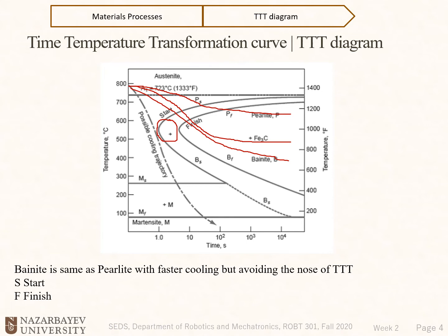So you see that we couldn't have martensite if we change temperature slowly, but we could have a different structure, which is martensite, and it is much harder and, let's say, stronger than other structures of iron if we change the temperature fast. Now we know why heat treatment is very important, and how heat treatment could change the mechanical property of materials. We don't want to go into more detail, it's beyond the topic of our course, and that would be enough for us.